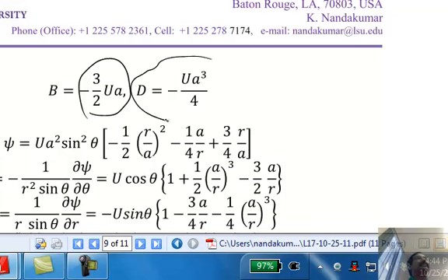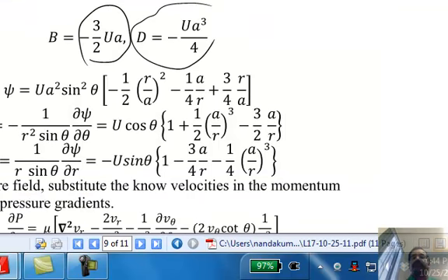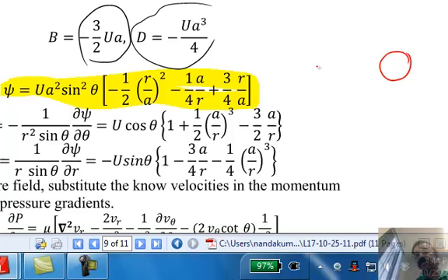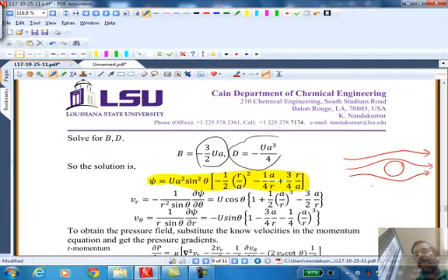So now you have actually satisfied the boundary condition, satisfied the differential equation, and the stream function. You have an analytical expression. You should be able to plot this. Okay, and when you plot this one, you will find that the streamlines look like that. Symmetric, of course. Okay.